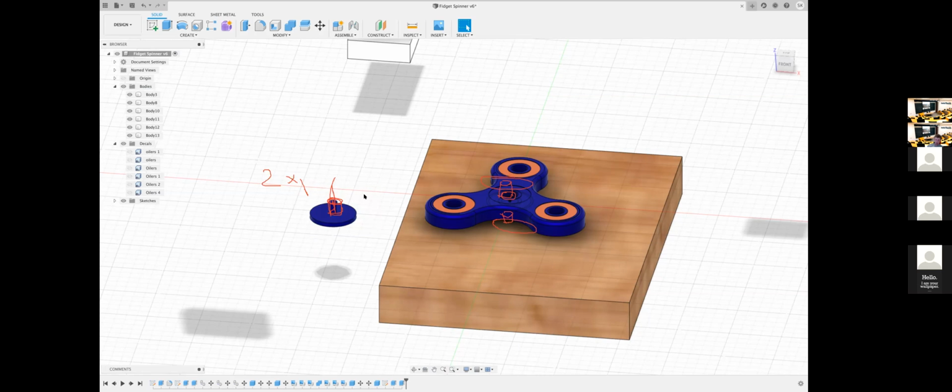Yeah, that's fine. If you're getting someone else to print it, just say I need two of these and one of these. They will do their slicing for you because you don't really know what kind of printer they use. So for you to slice it, it's not practical because the slicing process is designed for the particular printer that will be used for manufacturing. Since you don't know what they're going to be using, you cannot really foresee what parameters to put in it.